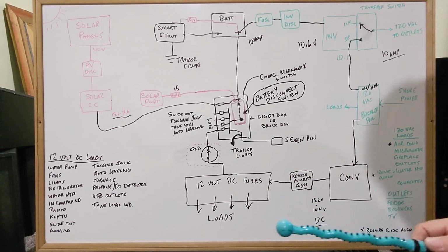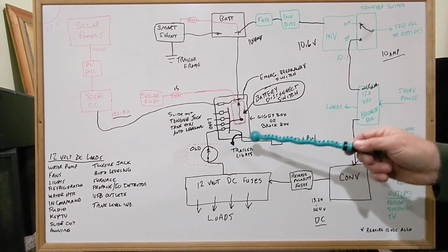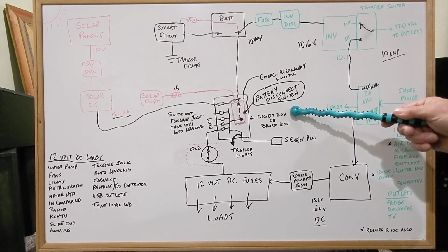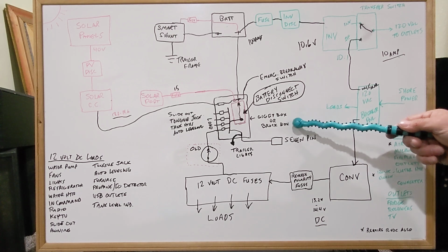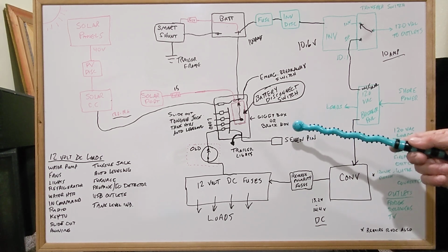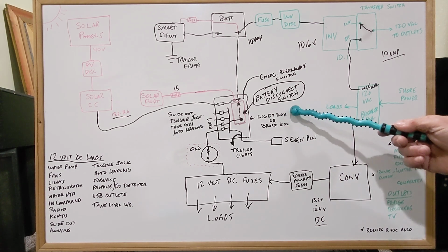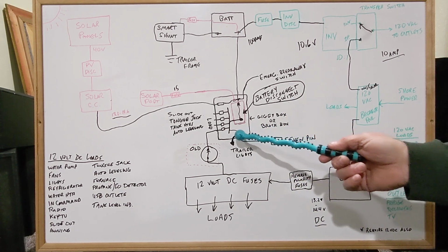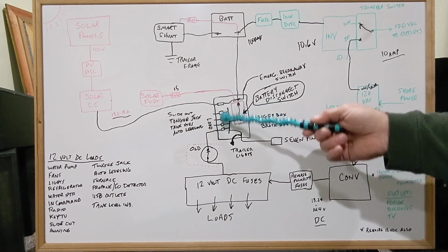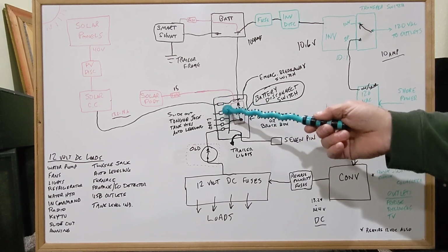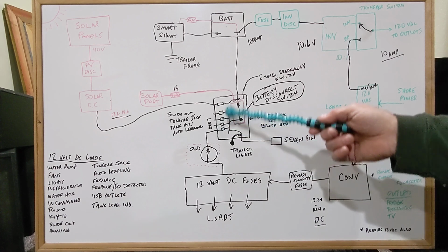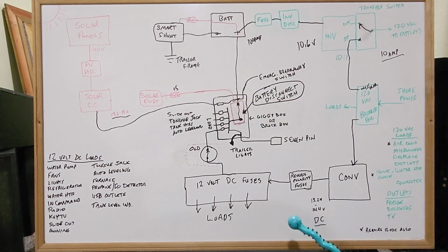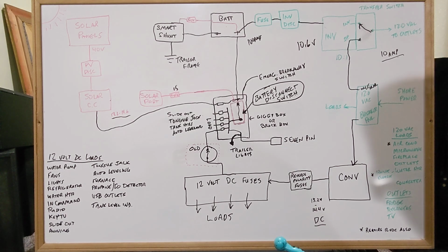So that's the difference between what used to be and what they have now. In 2019, they started installing Giggy boxes on the travel trailers, and in 2022, they started installing the Brock boxes on the fifth wheel trailers, named after Mr. Giggy and Mr. Brock, the people who designed them. Basically, they took these auto-resetting breakers that were just sitting out in the weather on the tongues of the travel trailers or mounted to the wall, and they put them inside of a box to protect them and make the wiring more organized. So that's why they did that.